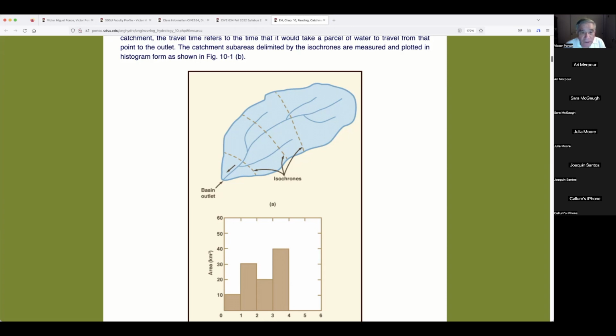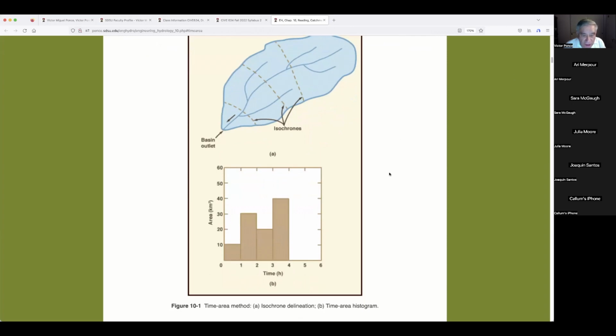Anyway, so we calculate the time of concentration, and here we not estimated, we adopted 4. And so what we're going to do in here is what is called the isochrones. If you remember, iso means equal and chrones means time, in, I believe, Greek. We borrow a number of words from the Greek language, right? So isochrones means equal time. That means that these can be plotted. For this, you've got to manage the time of concentration, of course.